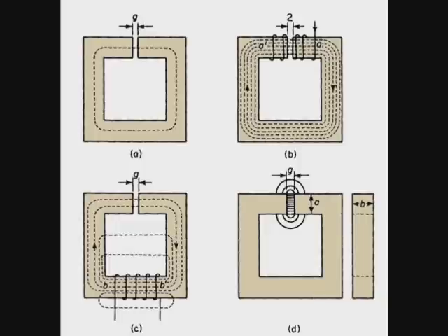In practice, the rotor of an electrical machine will be separated from the stator by an air gap. Let me show you what the air gap is. In order to maintain the same flux density, more mmf is needed in the core. The core medium and air gap medium are represented by reluctances. Here are the equations.